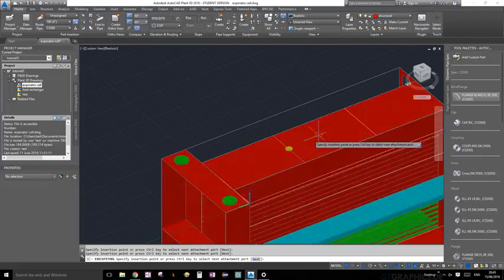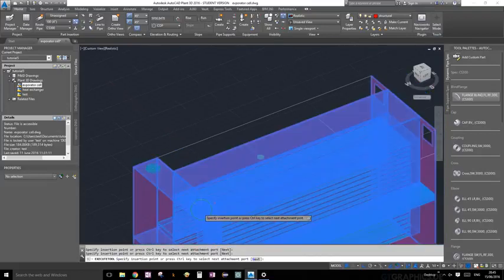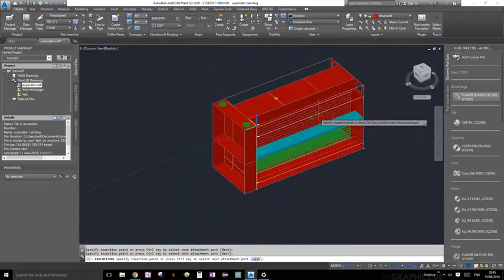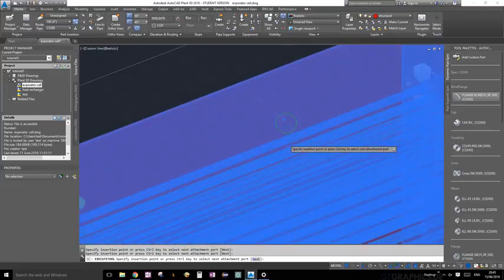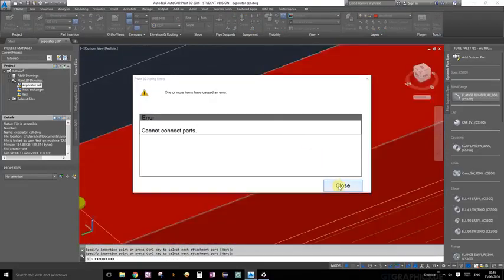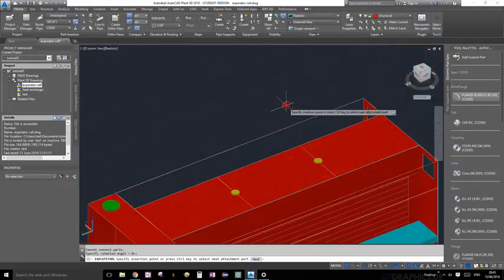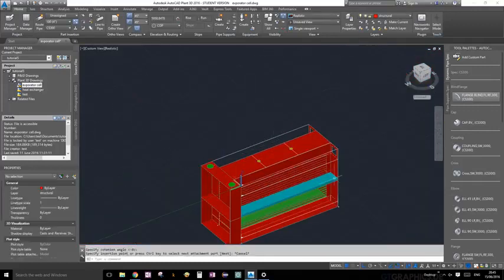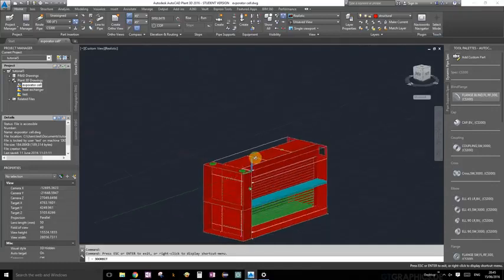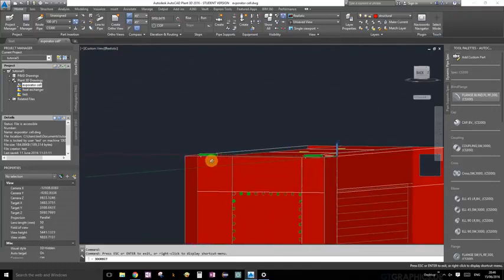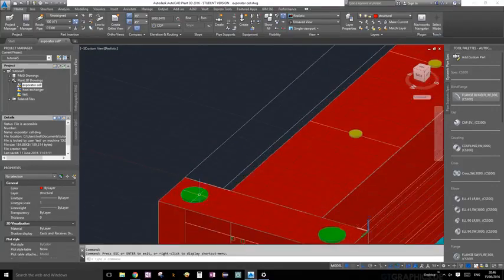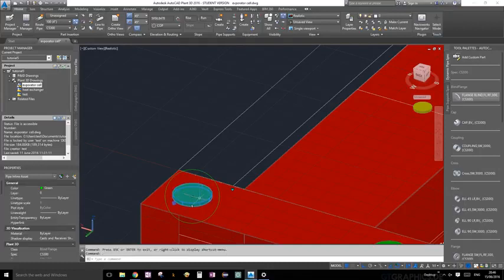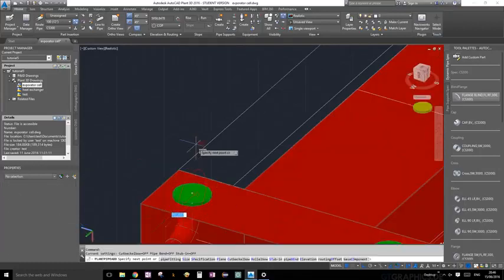See, now our blind flanges are actually going to show up in proper size, which is kind of nice. So that's why it's important to define your flanges first, even though nothing shows up. Now as you can see, our flanges have shown up. Oh, I've done it upside down. Okay, no, perfect. Now what you can do, if you select your flanges, if you click on this plus thing,